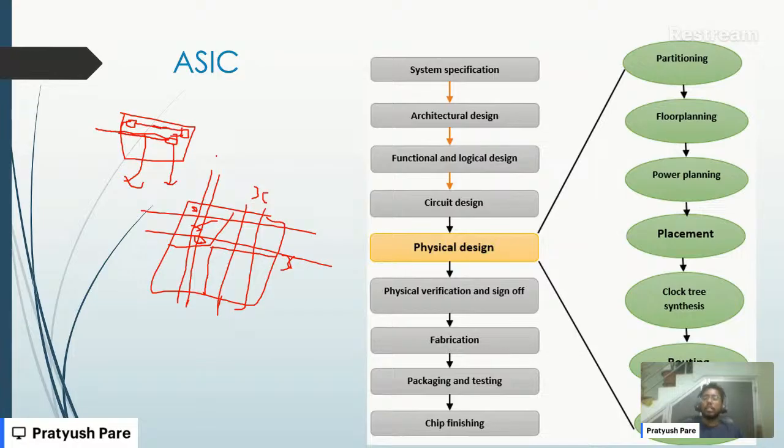And then the routing, which I already told, I want to connect this IP to this IP. That's where the routing comes into place. And at the end, the most important thing everyone talks about, that is the timing closure. You need to close the timing, and Vivek, that's the thing where STA comes into the picture.